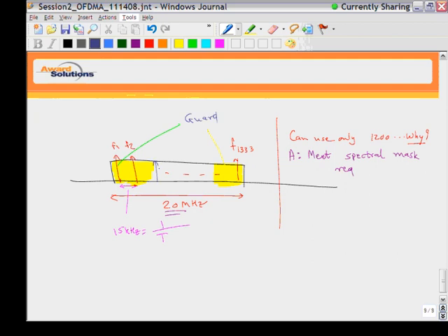So the last subcarrier will transmit. These are 1200 active data subcarriers, and these are guard. Let's say this is the transmit signal power, then it will go down, go down, go down. Similarly, this side will go down in signal strength.